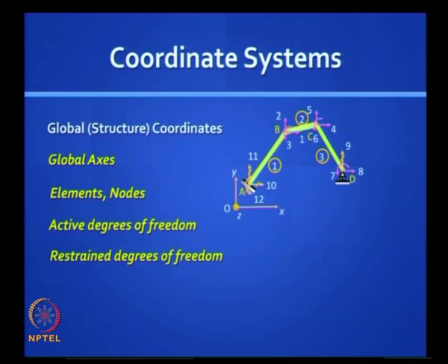So with this we have captured all the displacements at the different joints, D1 to D12. Some of them are active, some are restrained, is it clear? And by the way, restraint does not prevent you from including support settlements, but then it is still a known quantity, usually 0 but it can be non-zero, okay.